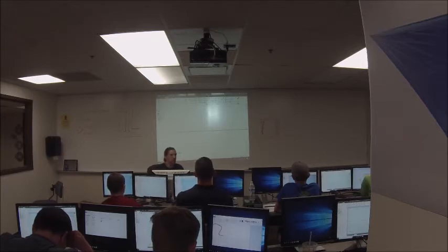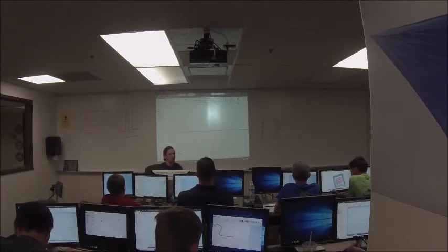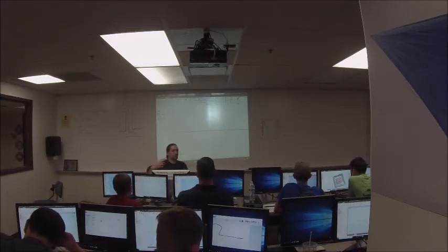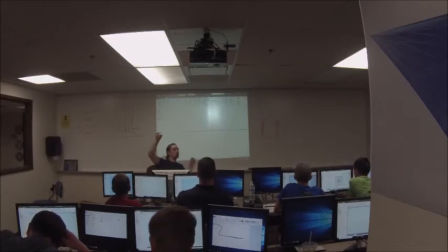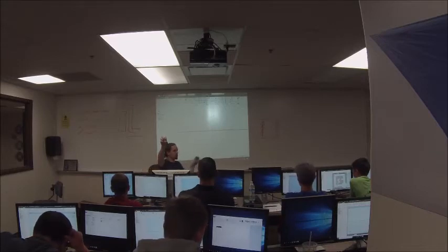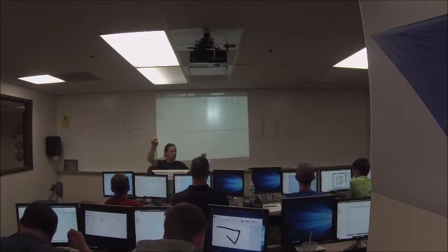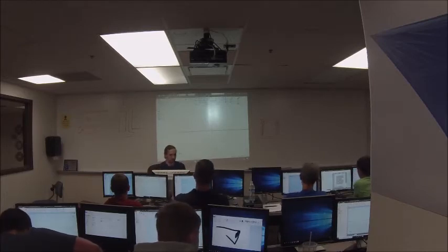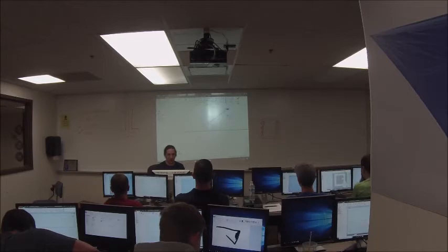The big one is coincident, which is a little bit of a weird one to understand just because it kind of runs under the radar most of the time. But if you think of a line, it has 2 points, one at each end of the line. More technically, I should call it a line segment, but in Inventor, it's a line. So a line has 2 points, an end point on each end. You don't really see them, but when I'm clicking and making a line, I'm clicking where I want the endpoints to be. And then you can go back and hover over, and you see this little red dot show up if I'm hovering over the endpoints.